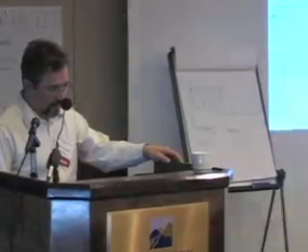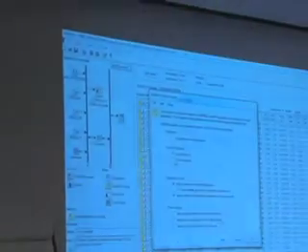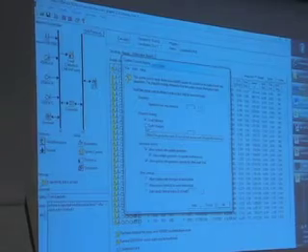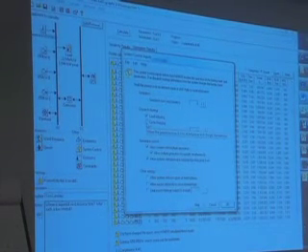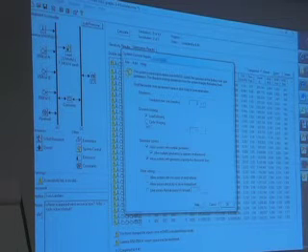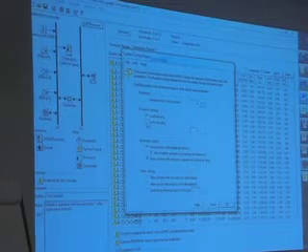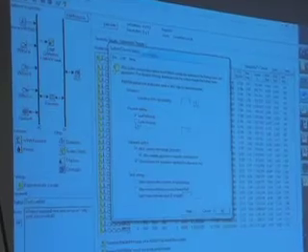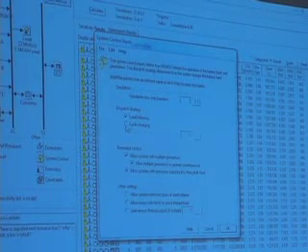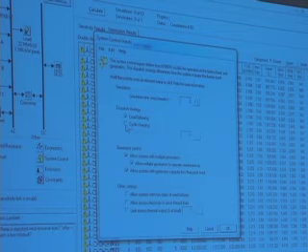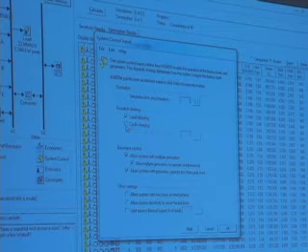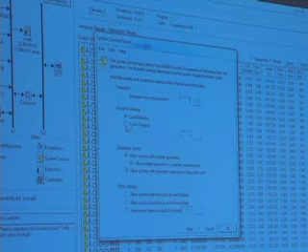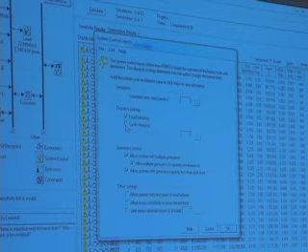So we have two basic load dispatch strategies, load following and cycle charging. Let me start with load following. It's the simplest one. It basically says the diesel never charges the battery. The dispatch strategy is really about battery charging, because we often think about dispatch strategies in terms of the diesels, but that's actually pretty straightforward. We're going to dispatch the diesels to meet the load, and we're going to do it in the least cost manner.